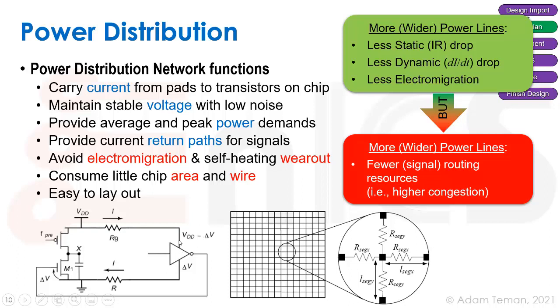And that's really bad. And the way that we are going to solve that is by giving a power distribution network. So if we had our rails of VDD and ground, which cause our rows, which would be these horizontal pieces, that's a long wire, and if we need to get into a gate in the middle, it's a thin wire. We're going to have a lot of IR drops.